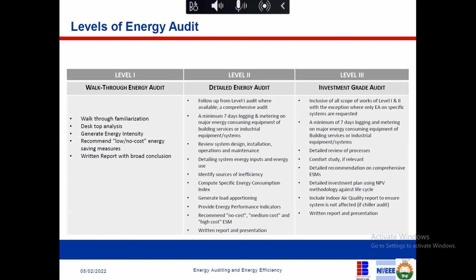So you can segment your equipment: cooling systems, lighting systems, motor systems, pump systems, and all of that. Based on significant energy user, for example if the cooling system is the significant energy user, you can recommend that the owner of the facility proceed and do an investment grade audit only on the cooling system so that they can implement it.